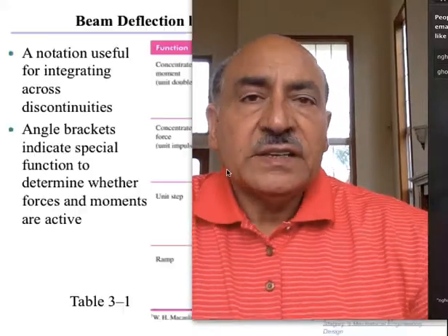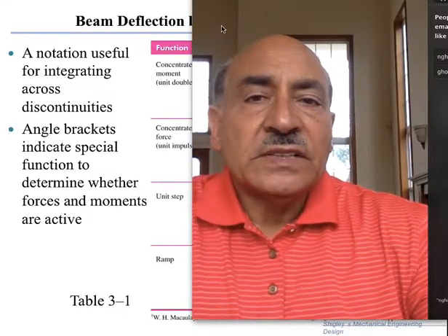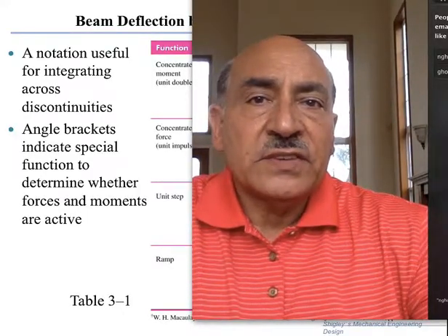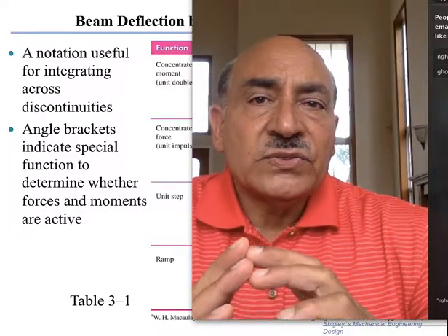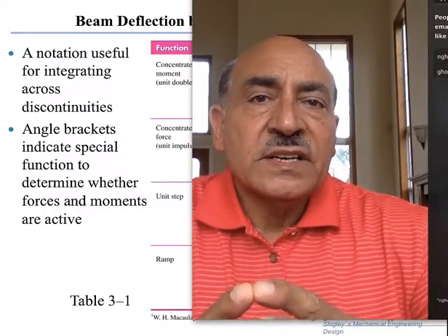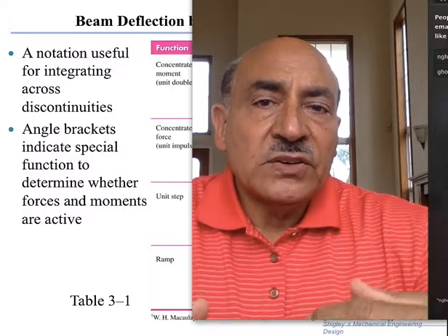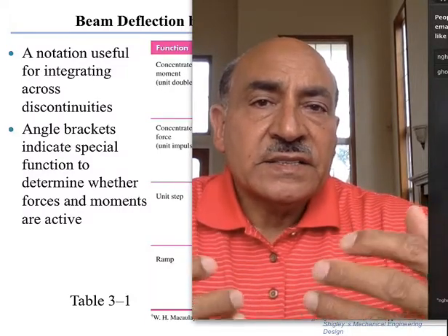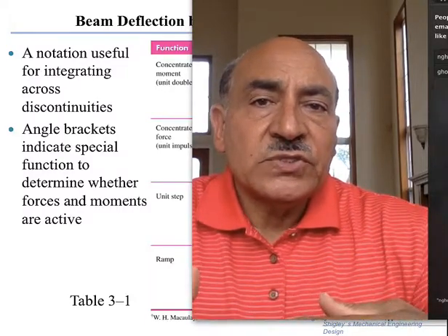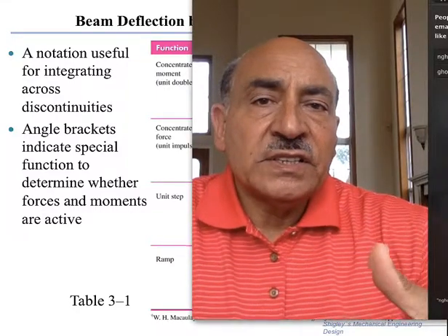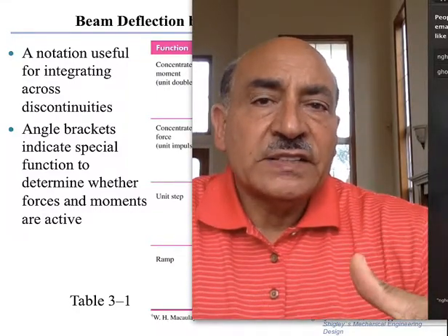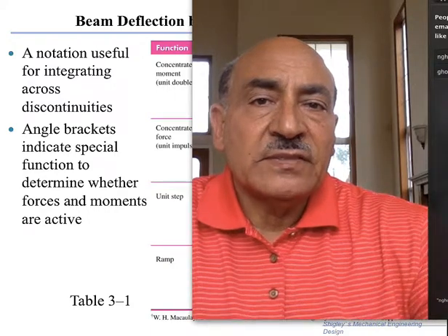Here I'll start discussing singularity functions as a way to mathematically express the loads, and then from the loads, by successive integrations, we are able to find the shear, and then the slope, and then the deflection.